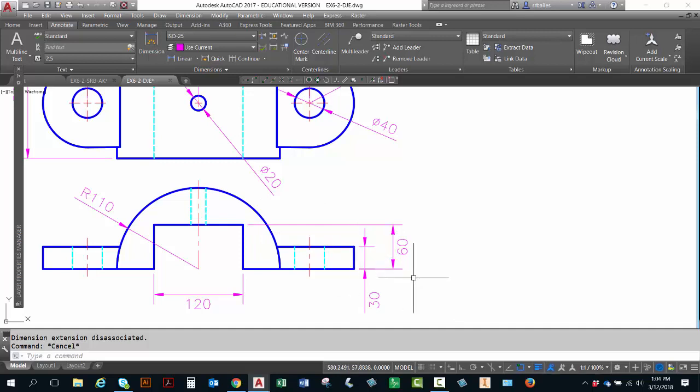Remember, we want like 10 millimeters, so I'll demonstrate 10 millimeters for your first line. No closer than 3/8 or 10 millimeters for your first dimension line. So let me just draw a line, and I don't even know what layer I'm in. I guess I'm in dimensioning layer, and I'll go out here 0 degrees and go 10 millimeters. Okay, so you're good. There's 10 millimeters.